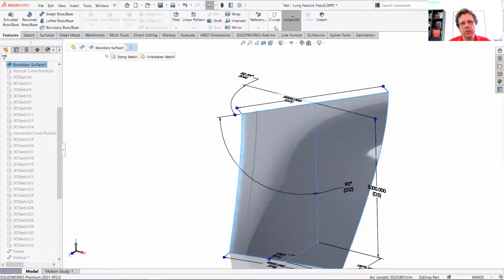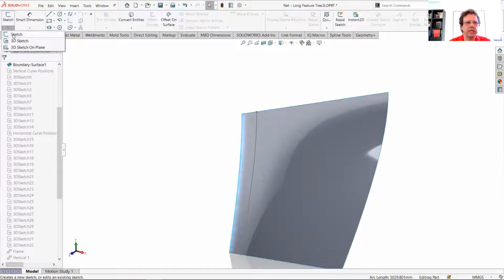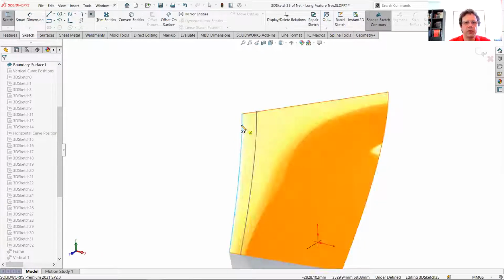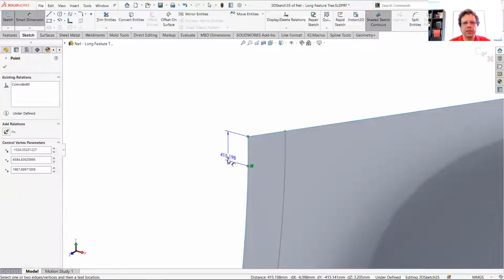One is to use reference points. Because one thing about reference points, you can specify the distance along the path. Isn't that cool? And also, when you use a reference point like this, you can actually use the ability to create almost like a pattern of reference points. So extremely, extremely useful, right? It's a different thing to say 500 measure along, it's kind of the length of the segment of the rope versus simply going to a 3D sketch and putting a point here and measuring the length this way, from here to here being, let's say, 500.